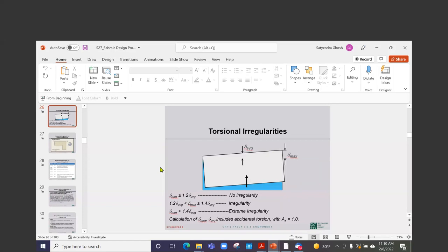From the definition of soft story and weak story, we know what they are, but you didn't tell us how to evaluate them. You did. Dr. Ghosh went over it. I don't know what you mean by evaluate. I specifically said strength is the shear carried by the lateral force resisting element, and stiffness is the reciprocal of deflection.